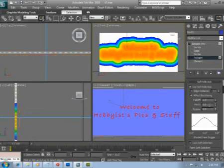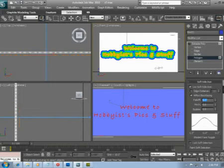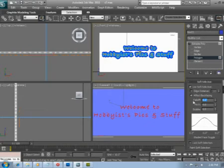Setting that to 1 is still way too high. We want blue or even some white between the letters in the top view. Otherwise our text is going to be all run together and unreadable. 0.3 is looking better. 0.2 and 0.18. There, that should give some separation between the letters.